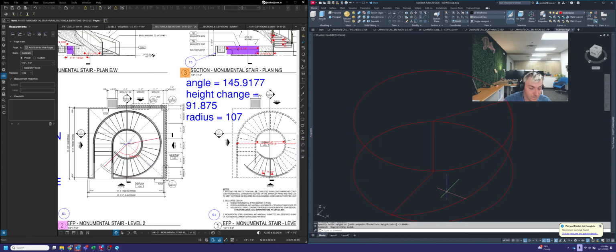And that number of turns is why this needs to be as far back of a decimal as you can go, because the more precise you are, the less likely your helix is going to end up going a little bit past this point. Or, well, it shouldn't go past this point, but there's a potential it could move past the stop point here by a small bit. So the closer you can get to an accurate decimal, the better chance you have of this stopping right where it needs to stop here.